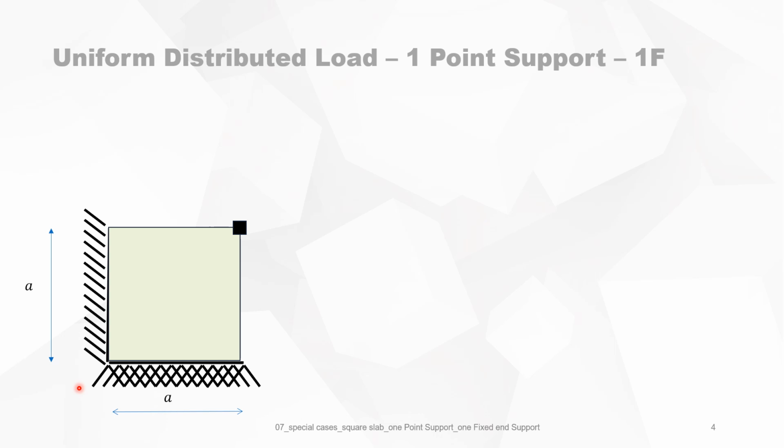We are now looking for the maximum bending moment by means of yield lines. We have to determine the axes of rotation. So this is at the support. It is one axis of rotation. This is the second one. And one axis of rotation goes through this point support.